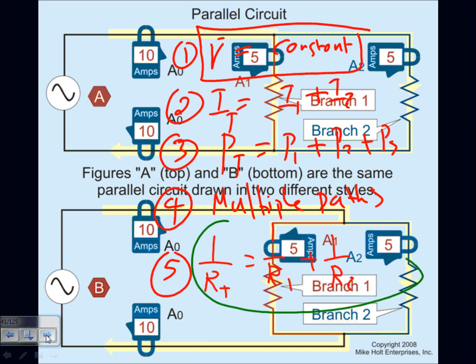And again, you have done a lot of calculation for this, so I'm not interested in the calculation, I'm interested in the concept. Concept number one here, very important: constant voltage. This is where you get your 480 volt, 208 volt, 240 volt here in the US. It's either 480 or 208, it can't be the same. The panel cannot be 208 and 480 at the same time. You have to choose constant voltage.